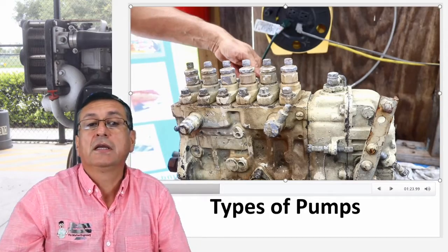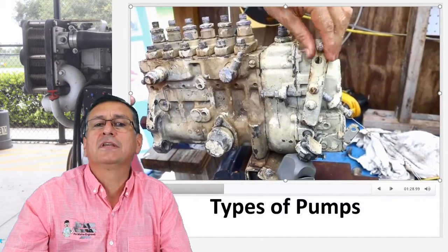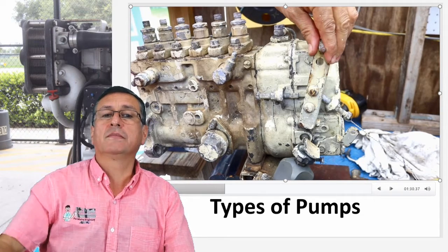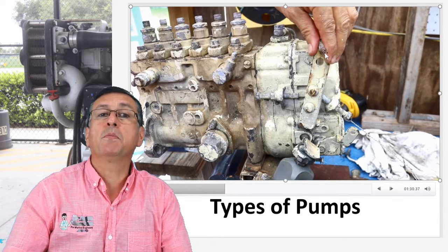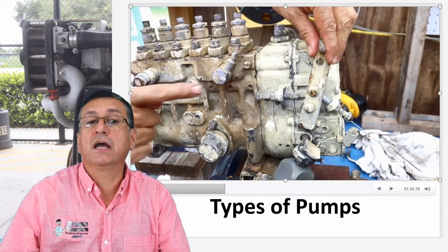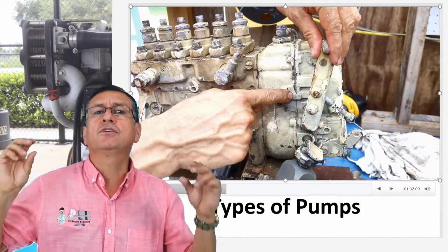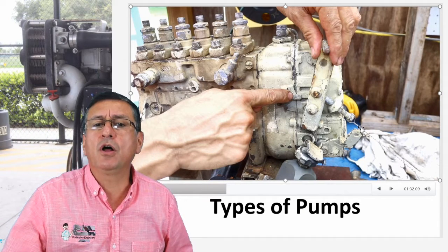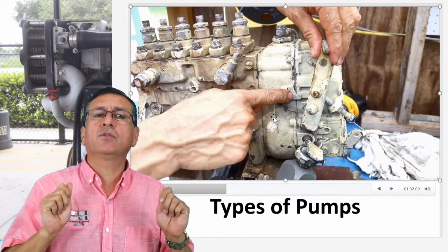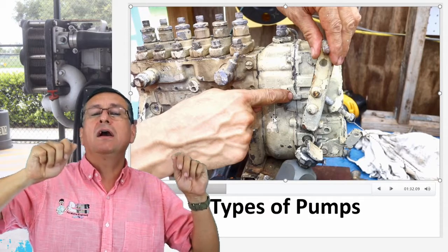Okay, my friends? This is the return, and this is the handle. That's the handle for the RPMs. This is the handle that is connected with the console, with the control on the console. Yeah, at this point, the cable is connected. All right. This is the handle for the RPM, and you have two bolts. One bolt for idle, and the other bolt to adjust the wide open throttle. Normally, those bolts have a safety wire over there, in order to prevent people from modifying the wide open throttle and the idle.